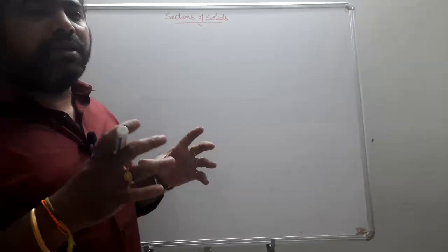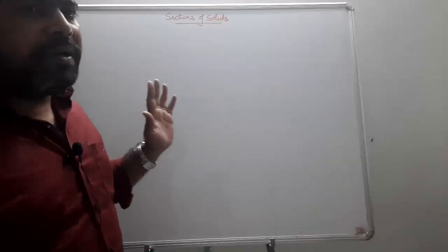Generally, when the interior of the object has a complex shape, the internal components which cannot be seen also have to be drawn with the help of dotted lines. We already saw in the projection of solids that whenever a corner or edge is not seen, it should be represented by a dotted line. If a complicated part has components that are assembled, and we see it from the front, side or top, we are not able to imagine the total parts. And if you place multiple dotted lines, it becomes more confusing and we don't understand what the shape of the object is.